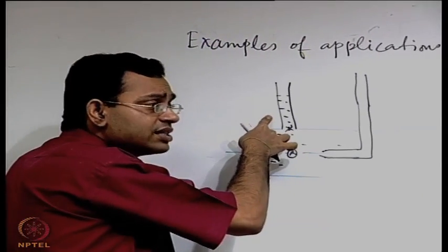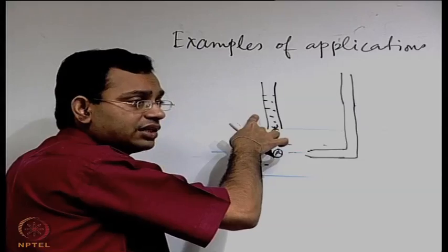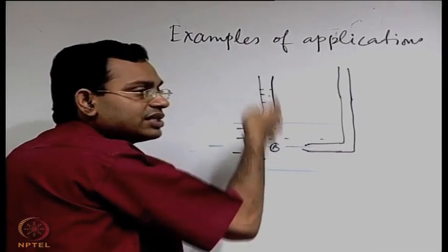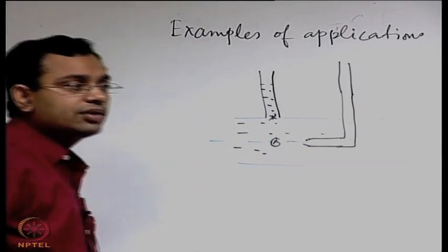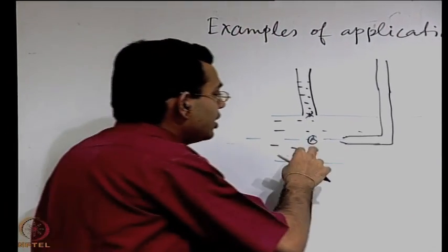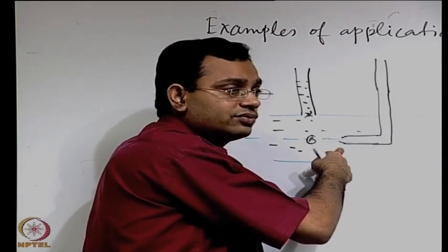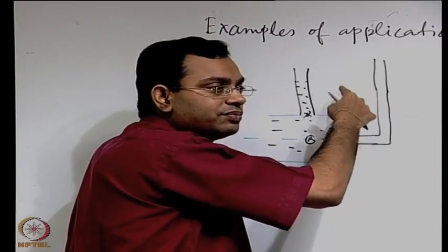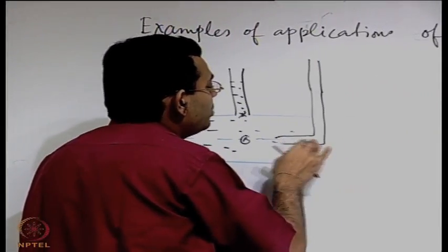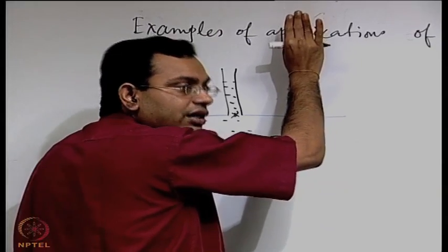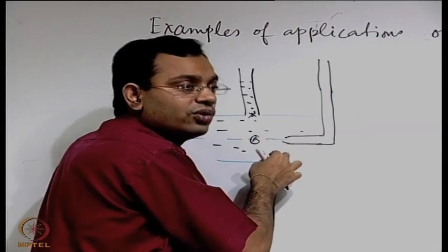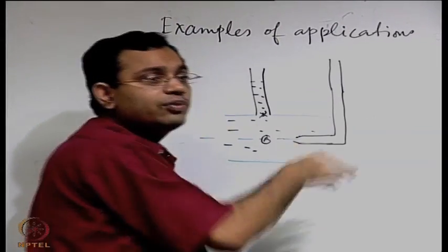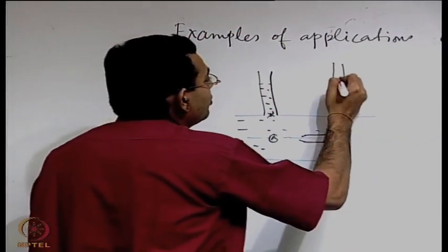See, this rise was a function of the pressure. Now the entire energy which was there in the flow, if we assume that the assumptions of Bernoulli's equation are valid, we have now made the kinetic energy 0. So the contribution of the pressure term plus the kinetic energy term will make the fluid go further up, because where else will that energy go? You have made the fluid come to a dead stop, you are assuming that it is a frictionless flow, so where will that energy go? It will obviously make the fluid rise to a greater height,